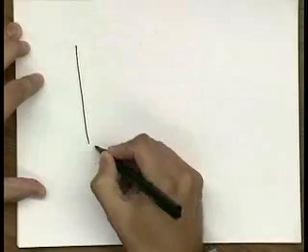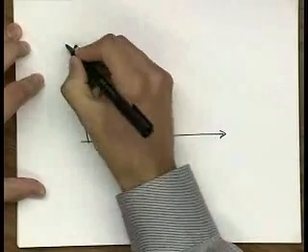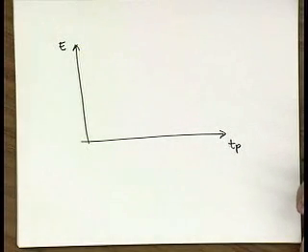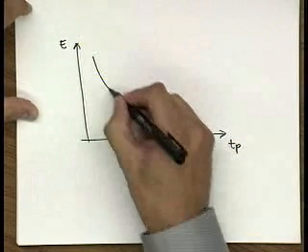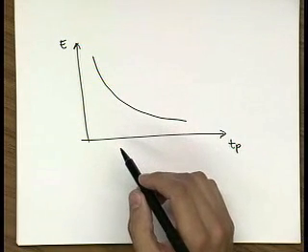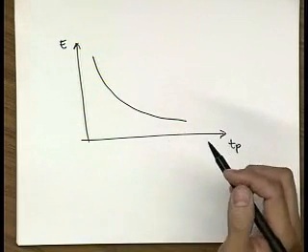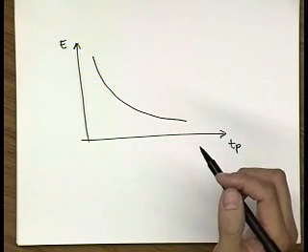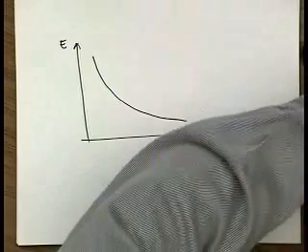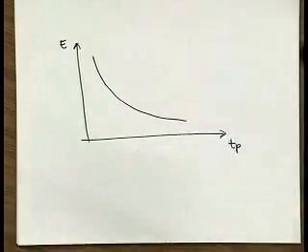So what you really have in each digital circuit on the energy and propagation delay axes, when you tune various parameters, for example supply voltage, which you are probably the most familiar with, you end up with some fundamental relationship like that. You have a trade-off. The faster you want to go, the more energy you need to spend, and so on. And when you actually plot your energy delay product on the same graph, what you get is something like this.